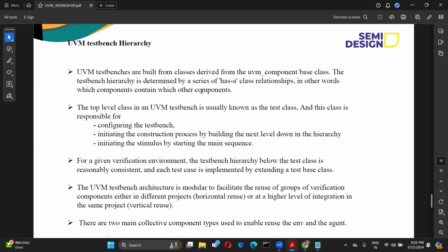Inside the testbench test architecture, when you observe, there are different TLM ports which we connect from one component to the other component. So any connections that are lying under the test will all be connected in the test. Basically the sequence to sequencer connection, whatever is there, using some start method, we do it. So that particular sequence to sequencer connection you can observe in the test class. These are the main functionalities that you will be observing in the test class.